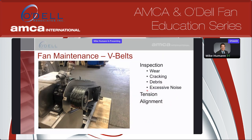So when you look at V-belts, a couple things really come out when you're looking at an inspection. You want to look for any wear, any cracking. Is there any debris in the belt guard or below where the belt is starting to deteriorate? Also, any excessive noise. Often at startup, you may hear a little squeal. As long as that squeal goes away, typically it's okay. It's just some belt slip when you're first starting the motor across the line, and it may squeal for a second, a couple seconds. As long as that goes away, it's typically not an issue.